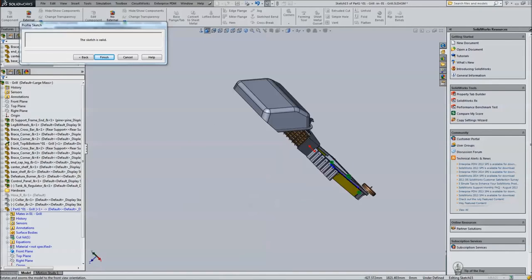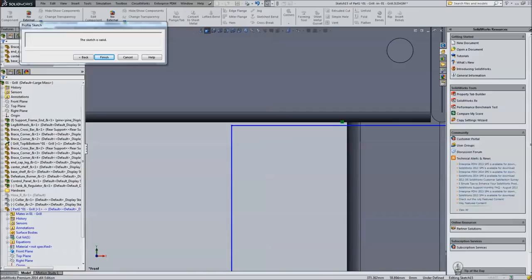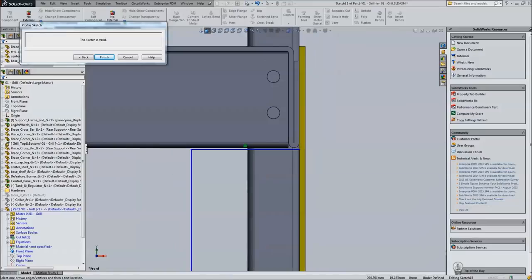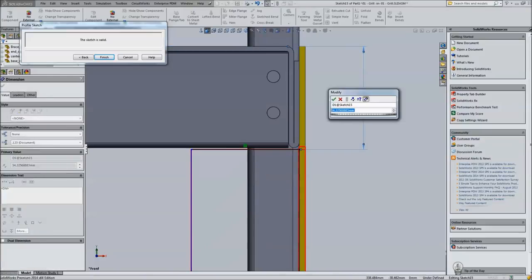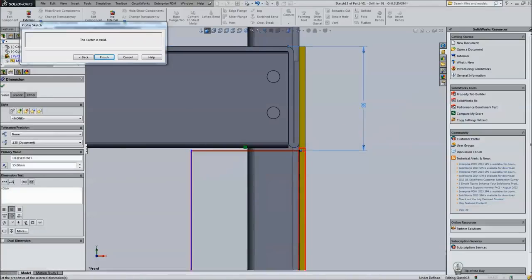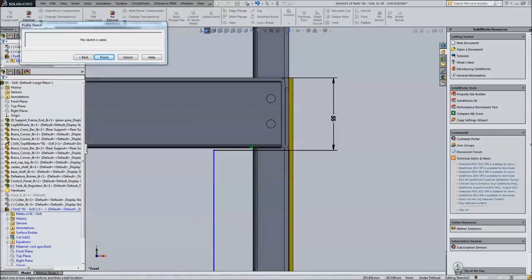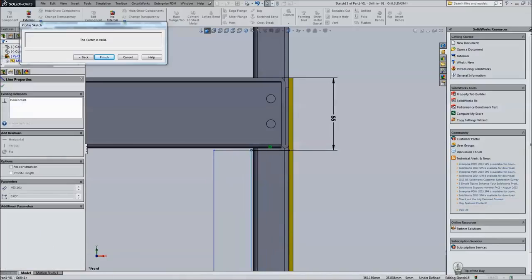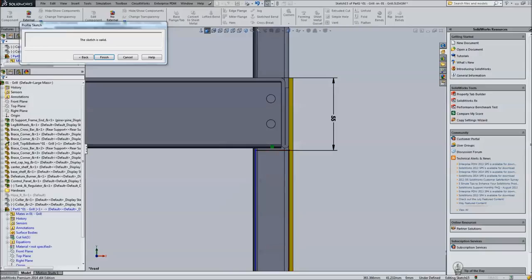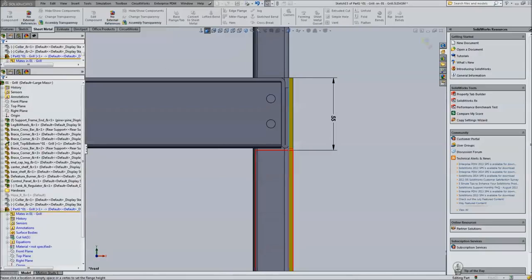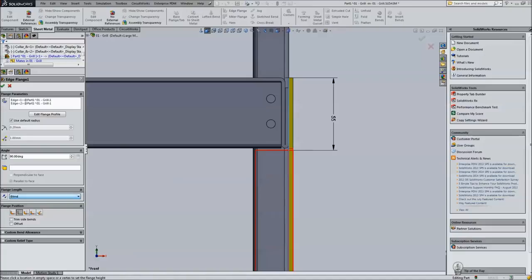I'm going to go to front view, go into dimension, and let's pick a dimension. Say from the top of the shelf to here, we wanted 55 millimeters. And same thing with this profile, this flange here. We can actually give it a length or a depth. The second we do that, let me hit back for a second. Notice we have blind and we have up to vertex.